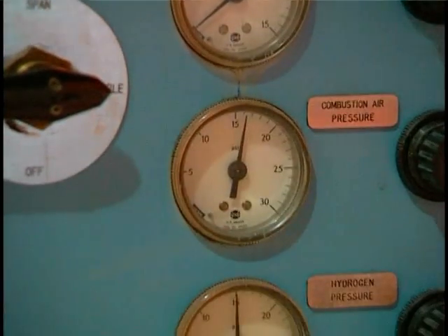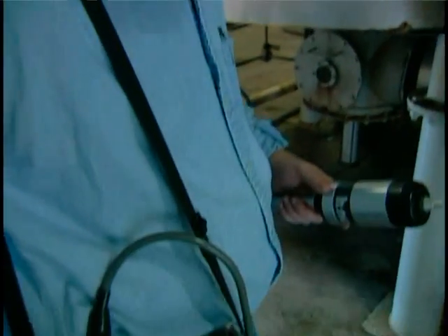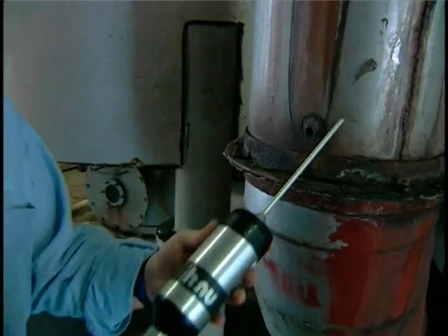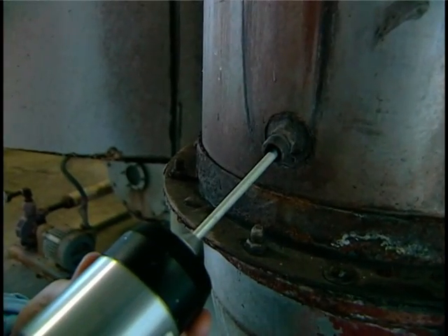If there is no permanently installed analyzer, the concentration measurements will have to be performed with a portable analyzer. Due to the limited pump capacity of these analyzers, measurements must be made in the portion of the outlet ductwork that is under positive pressure.